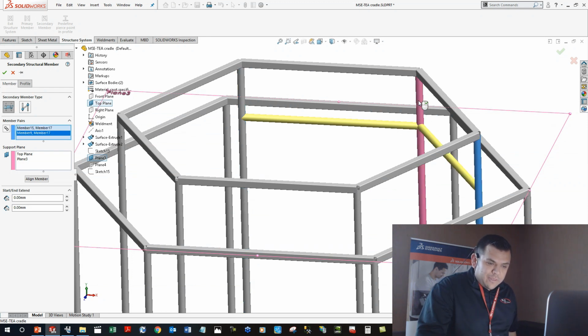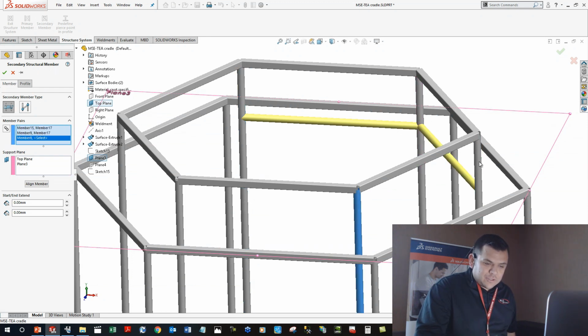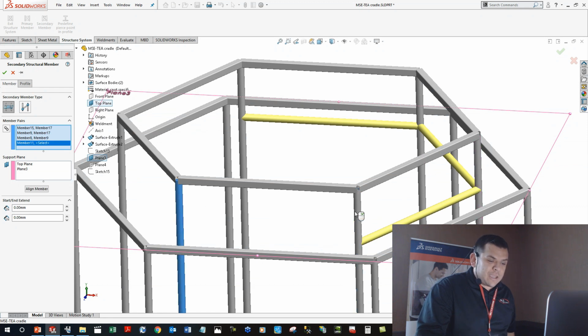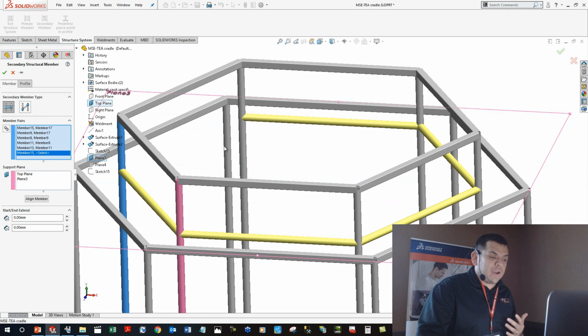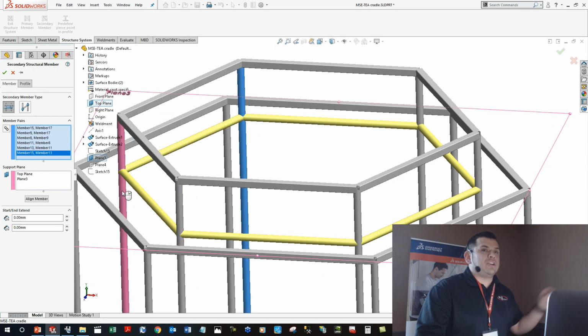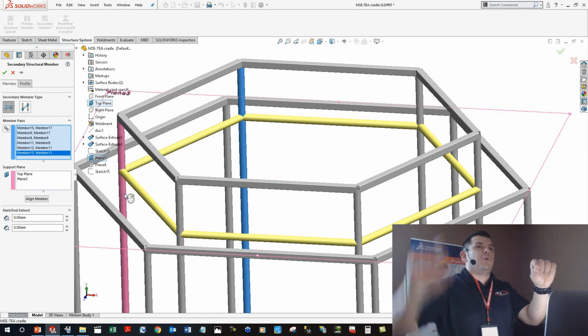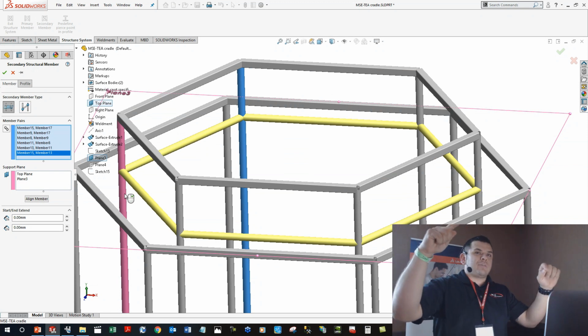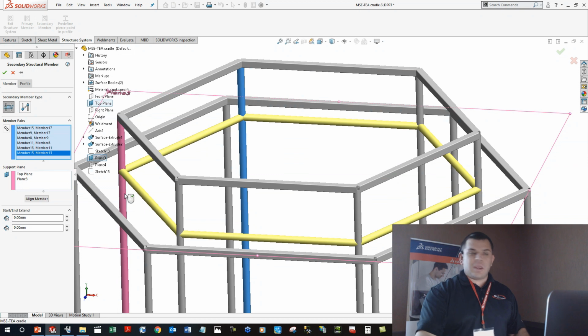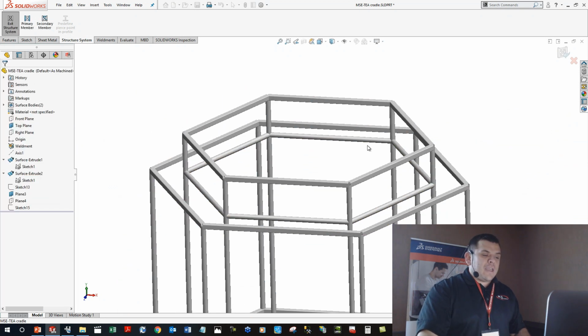So I'm going to come over here, I'm going to click these 2, I'm going to click these 2, and now instead of, okay, I've done this before in real life using the normal weldment tool. You would have to go and create a 3D sketch or a 2D sketch or a plane and draw lines. And then you'd go weldment, structural body, click, click, click, click, trim, trim, trim, trim, hit the green check mark. All that's gone. I hit this green check mark, and there it is.